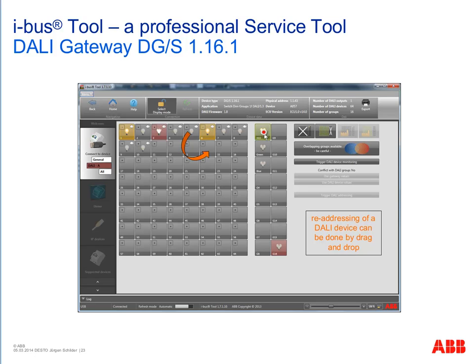So we press here, for example, group number 1, and press the plus button, and then these devices are added automatically to the DALI group number 2. Plus additional features: for example, we can reset DALI ballast to factory values, or we get more information, like when we have overlapping groups.